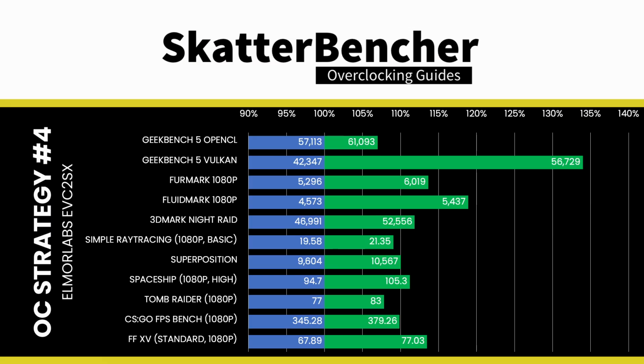We reran the benchmarks and checked the performance increase compared to the default operation. Working around some of the electrical limitations of the RX 6500 XT allows us to maintain a higher GPU boost frequency for longer. That results in significant performance improvements in workloads limited by the minimum GPU frequency or the maximum permitted power. We see a maximum performance uplift of plus 34% in Geekbench 5 Vulkan.